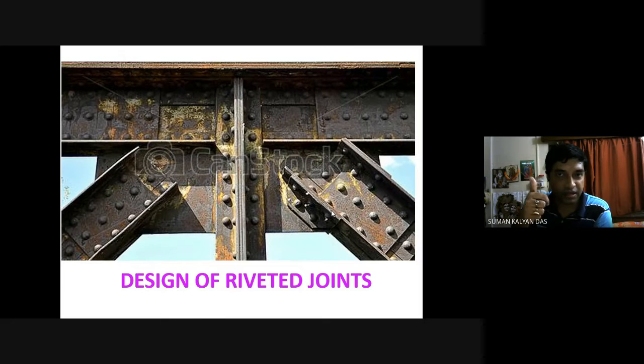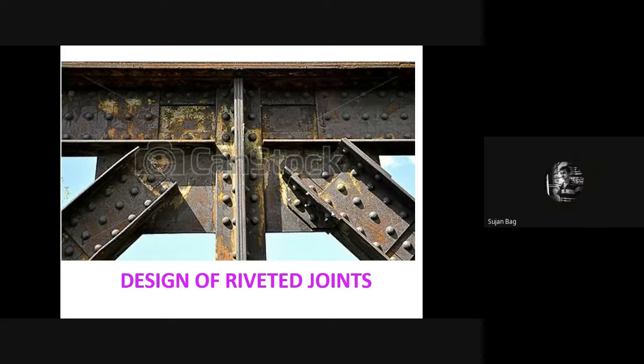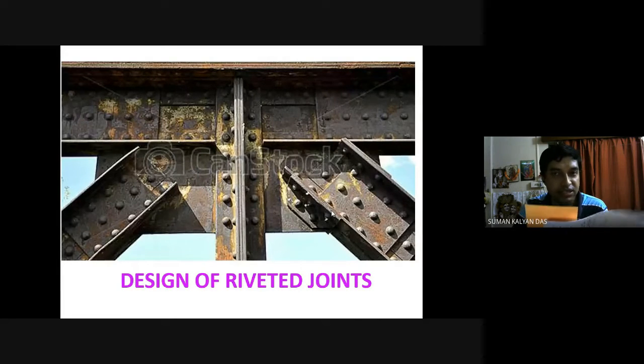Are you aware of the nominal diameter of your bolted joint, screw joint, from machine drawing maybe? Yes, sir. Outer dia. Yeah, there are 3 dias if you talk about the screw joint. The highest dia that we encounter in the bolt or the screw is the nominal dia, and with that only the bolt is specified.